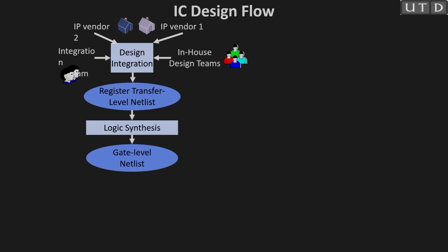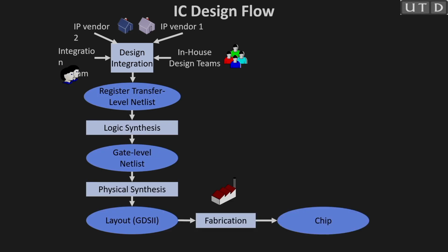If I go into a bit more detail, nowadays the chip is not a single thing, it is an SoC, a system on chip. So, you need multiple IPs. You bring the IPs from different vendors, and they give you an RTL IP. This IP may be developed directly by writing the HDL, or you write C code and then use high level synthesis to generate those IPs. So, you have different components brought from different vendors, and you integrate them at the register transfer level.